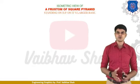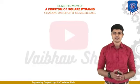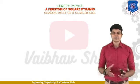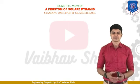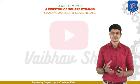Ready? So then after, let us move to create an isometric view of a frustum of a square pyramid. Frustum of a square pyramid means you will be having one pyramid. Pyramid means what? It's Egypt's pyramid. Always remember, you will be having the apex at the top. You will have a single base and the apex at the top. So it is a square pyramid.